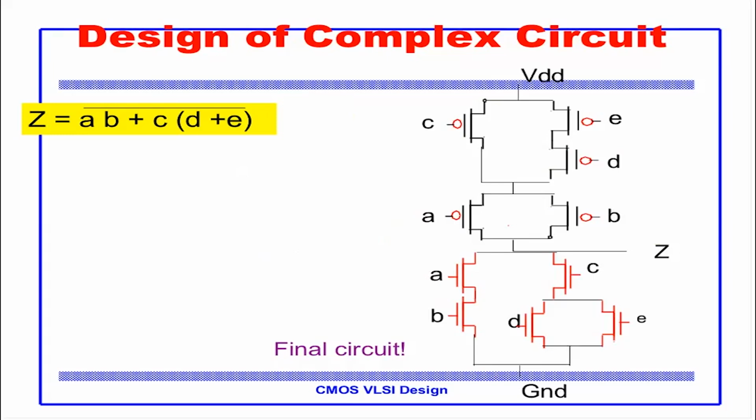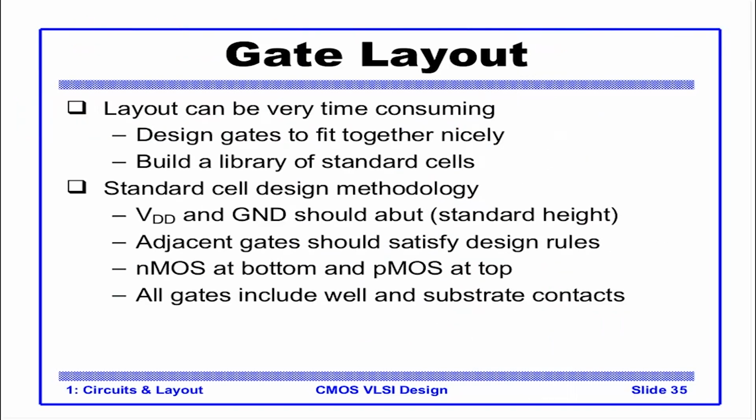We also saw that not all CMOS circuits or CMOS designs are designed this way. We also use the power of transmission gate and tri-state inverter to construct circuits such as MUX. But still, this is the most popular technique for complex logic circuits. Now let's look at how for a complex case we arrived at a static CMOS circuit. With the circuit in place, you know how many transistors it's going to take.